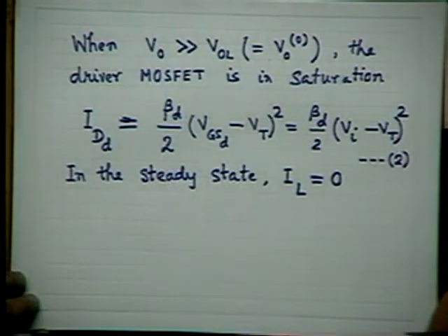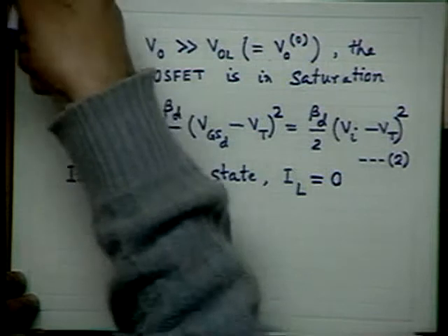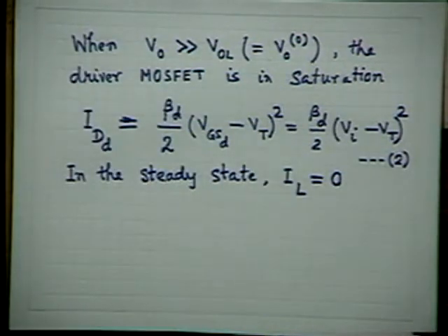Am I correct? Because what kind of load is it facing? It's a capacitance, pure capacitance. So in the steady state, that capacitive current is 0. No question of any current flowing through the capacitor, because this is MOS capacitance with a very, very high leakage resistance of the order of tens of mega ohm, in fact maybe 100 mega ohm also. Purely electrostatic device. Please remember, that is why MOSFET is so good from various application points of view.